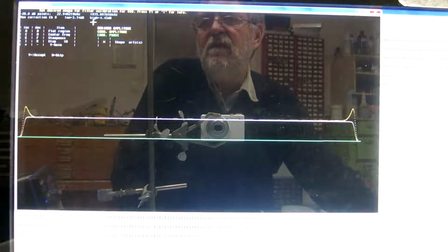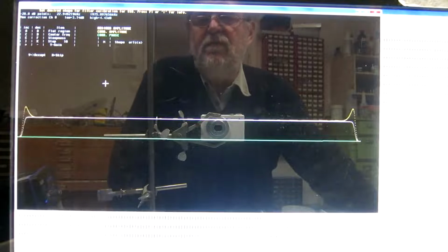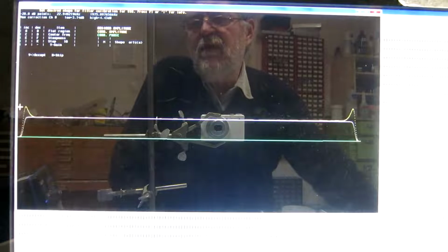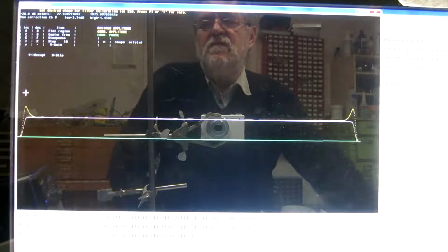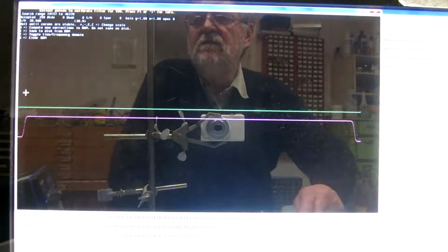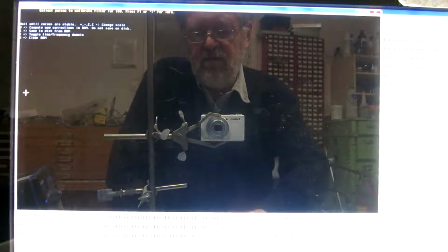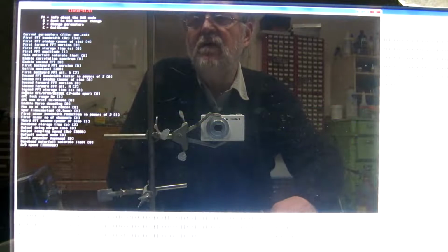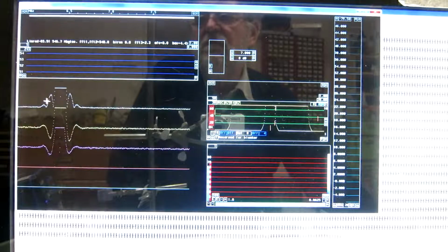You can see that here. Further than this is not reasonable to go, because the noise figure will drop by these 4 dB at the edges. Accept, and then save, and X, and go back to the processing screen.